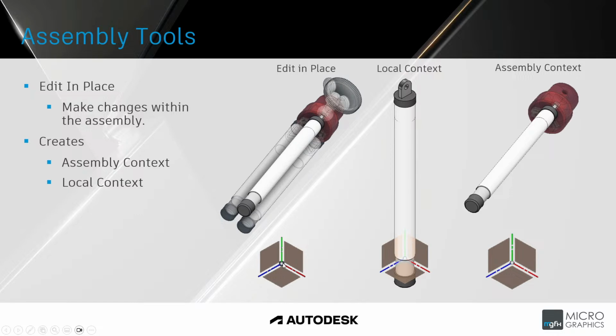Notice the origin position here relative to the head of the assembly. So the origin is not located at the foot of the tripod leg or at the top of the tripod leg. It is out in space, away from the component.